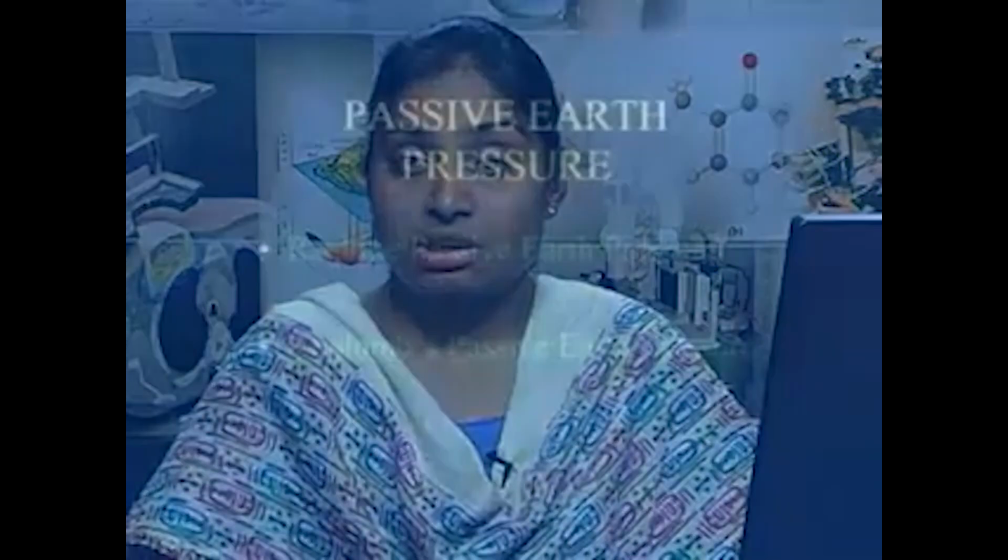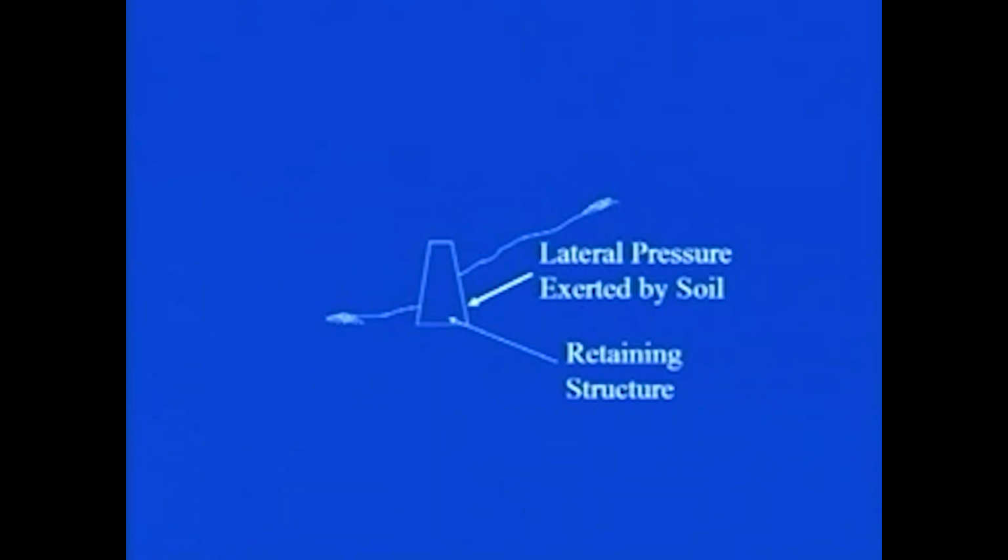Now, this was all about your active earth pressure. Now let us come to the third one, that is when the wall is moving towards the soil, and I explained earlier in the previous class that this particular condition corresponds to passive earth pressure. From common sense you can find out, this soil is exerting lateral earth pressure on the wall. So wall is always having a tendency to move away from the soil. In what case will it be moving towards the soil?